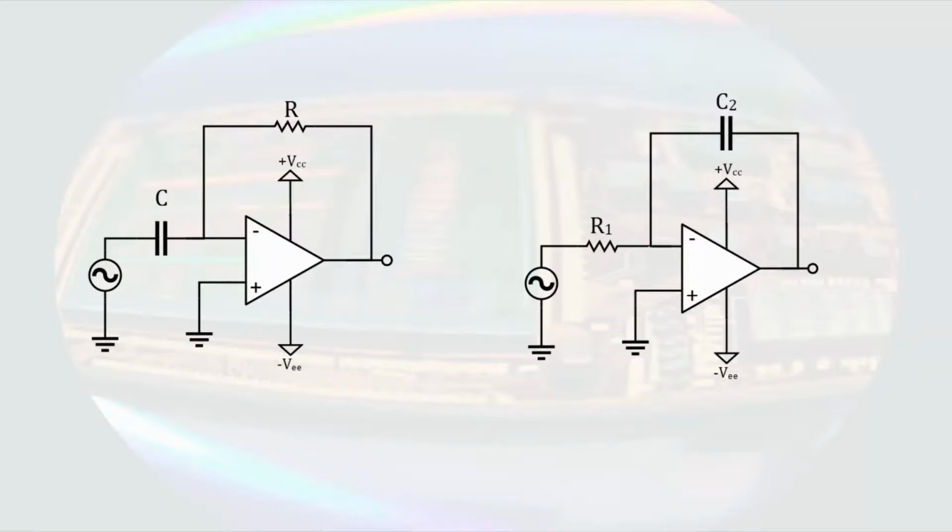Remember that the feedback from the output to the inverting terminal is what makes the amplifier stable. An open circuit in the feedback means that the open loop gain will apply to any slight offset voltages that might exist at the input. A millivolt can easily be enough to cause the operational amplifier to saturate. In addition, for any periodic function, the gain of the amplifier will depend on the frequency of the input to the point that the gain increases or decreases without a mathematical limit.